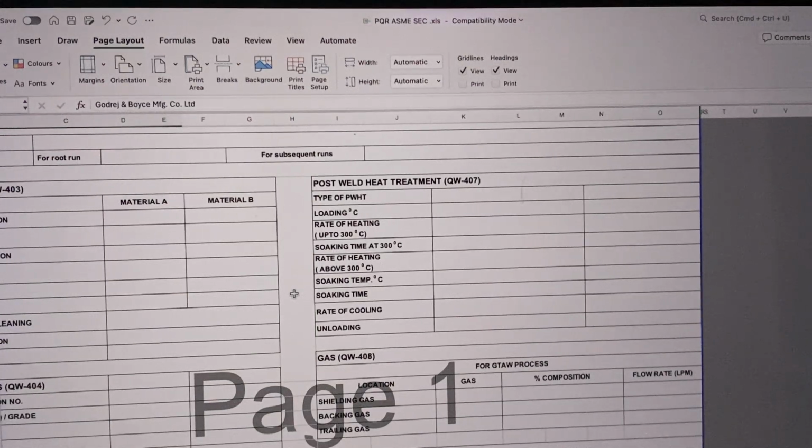And if we can record along with the size, the weight of the overall PQR plate, so the quench effectiveness, we can assess the tank size, the quantity of the oil, quantity of the water, if we have used the mist spray, how many nozzles were used.